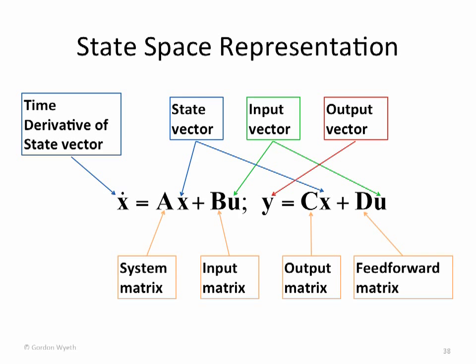Companion matrix form looks something like this. But you could do exactly the same thing if your transfer function was in Z instead of in S, right? You could convert it to a discrete time state space representation, just like that. Everything that you've learned that you can do in continuous time, you can do in discrete time. So that would be an easy way to get going.